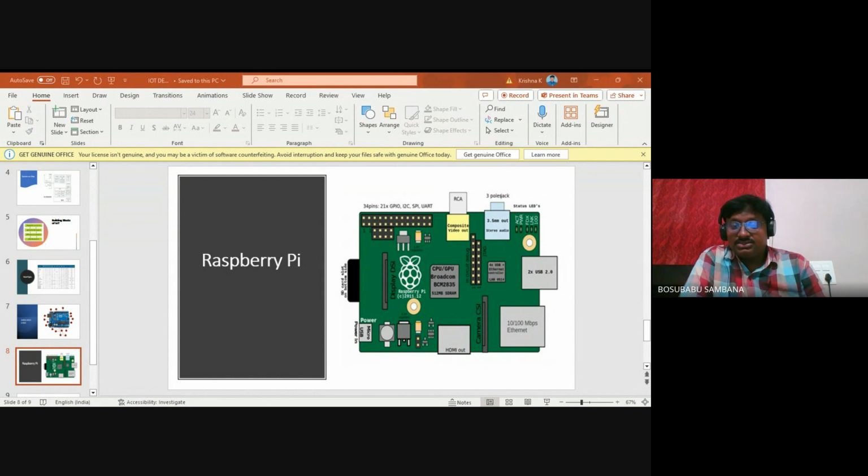The Raspberry Pi 3 is the first single board computer to feature both Wi-Fi and Bluetooth connectivity and a 64-bit processor. It has been in the works for a year, says Eben Upton, CEO of the Raspberry Pi Foundation. A quad-core 64-bit 1.2 GHz ARM Cortex A53 chip, 1 gigabyte of RAM, VideoCore 4 graphics, Bluetooth 4.1 and 802.11n Wi-Fi replaced the Pi 2 in this variant.